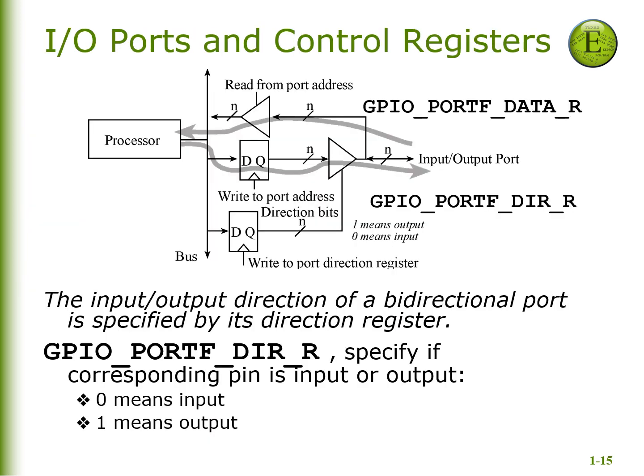I/O pins can be configured either as input pins or output pins. An example of an I/O port pin configuration circuit is shown here. The circuit contains 2 buffers controlled by separate control signals. At any one point, only one of the buffers is active. And remember, the role of the buffer is just to transmit the logical information from its input to its output. So for example, if we wish to configure the pin over here as the input pin, that is, the microcontroller wants to read data from the pin, then this will be the route. In this case, the upper buffer is activated and the lower buffer is deactivated.